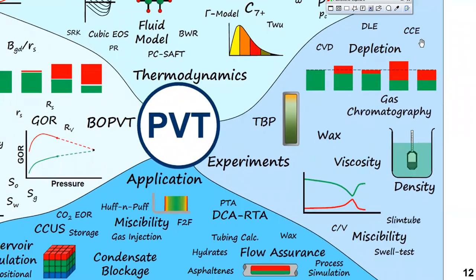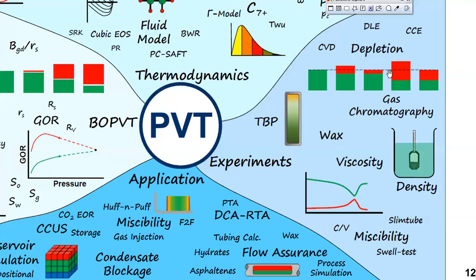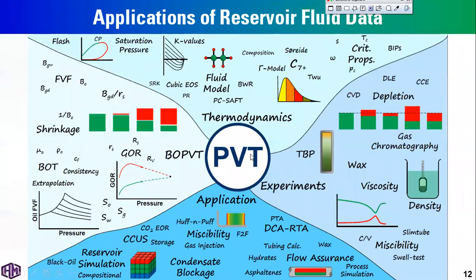Additionally, the study to simulate the production above and below the bubble point or saturation pressure, which is the standard PVT experiments: the flash or CCE, differential liberation, constant volume depletion, CVD. The fluid composition is very important. Also, the miscibility or slim tube testing, and so on. Or other thermodynamics is to study or to generate the phase behavior.